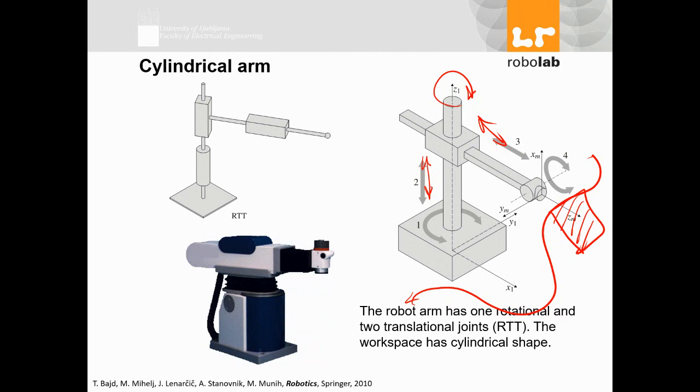Normally it doesn't happen, but let's say I have collaborative robots working together, and it is important that this robot goes from point A to point B and never enters this area, because another robot is working and coming and going here. In that case, it might make a slight difference if you consider this moving pathway, and also the dynamics, as I said: the forces you're applying, the torque you're applying, the energy you're consuming when you have these robots working.